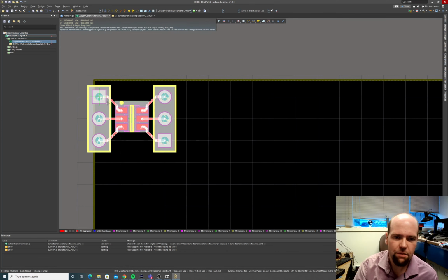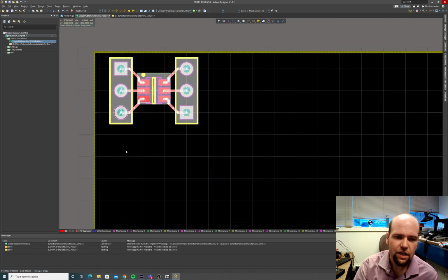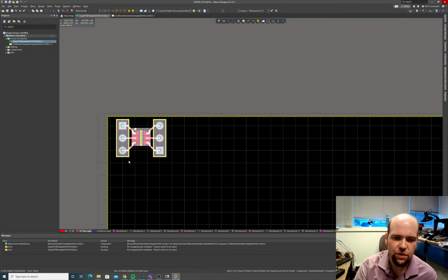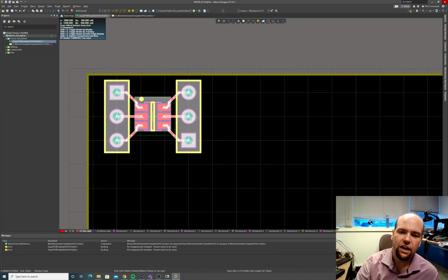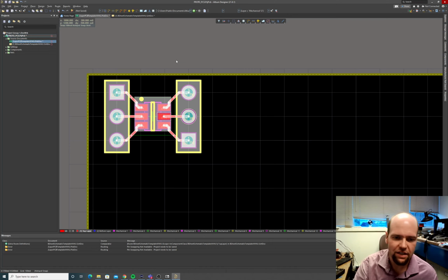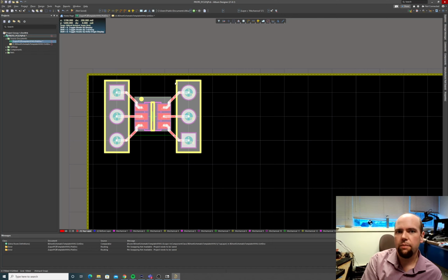Okay, now the question is, how big do you want to make these parts? One issue with these parts is if the board extends too far, you're not going to be able to access the holes on the breadboard. So if the board extends too far, you're going to be covering holes next to your board when it's plugged into a breadboard. So you kind of want to keep it a little tight. But the other issue is we're putting a lot of parts on one board. So when we're putting a lot of parts on one board, we're going to have to cut those parts out in between. So the perimeter of each part is going to kind of be set by how we cut it.